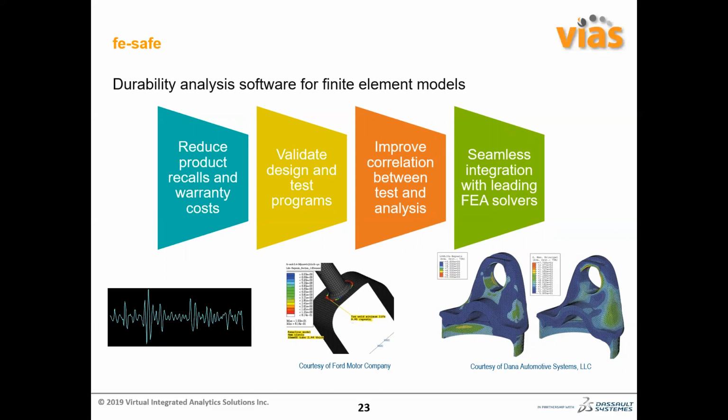Generally, people in the industry use metal fatigue calculation based on some mean stress criteria like the Soderberg criteria, Goodman criteria, or Gerber criteria. But those are not really very accurate, and I'll tell you the reason behind that, and I'll show you several examples. Generally we understand that if we are doing an FEA analysis for a particular kind of loading scenario, and we get a maximum principal stress at a certain location to be high, our observation from this mean stress based fatigue calculation is that that is the location where the failure is going to start. But that is really not true.